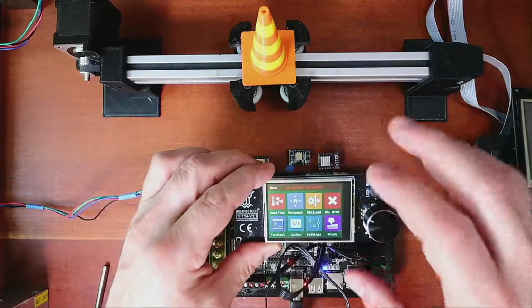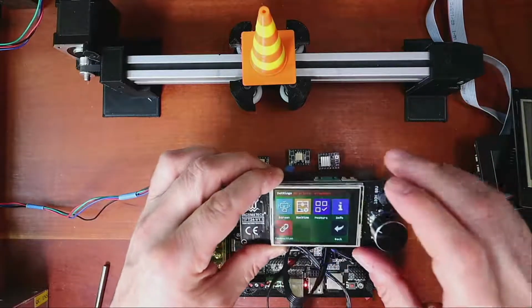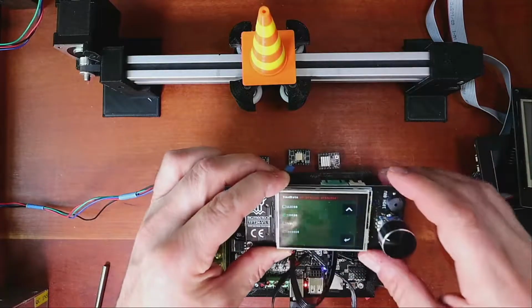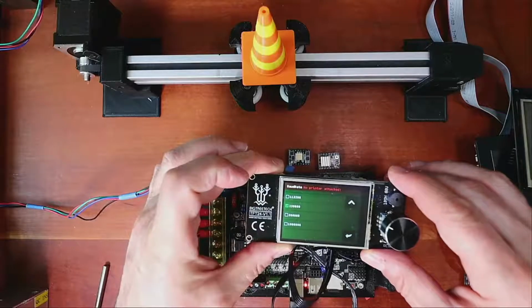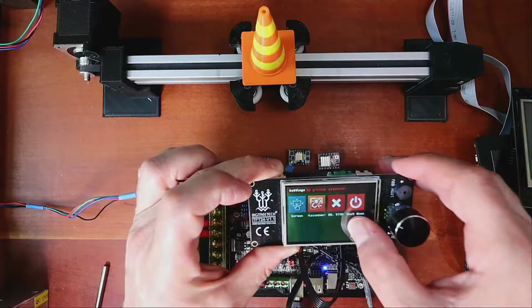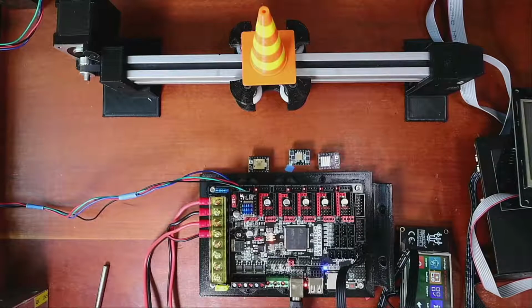So, no printer attached. One of the first things you can check for is settings. Then you're going to go to connection. Then you're going to go to baud rate and verify you're set to the right connection. If that is correct, then it's probably the setting in the firmware. So I'm going to put this down. I'm going to power down the system for a second.